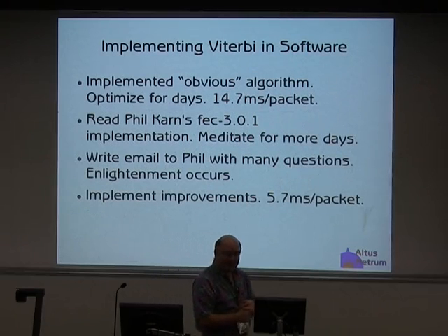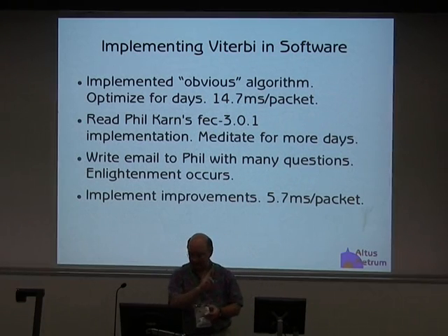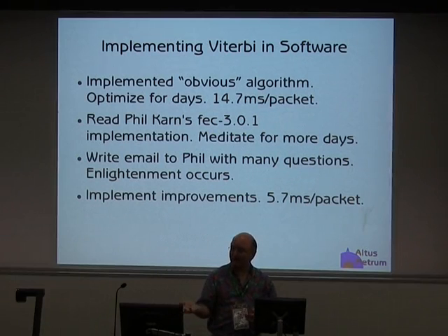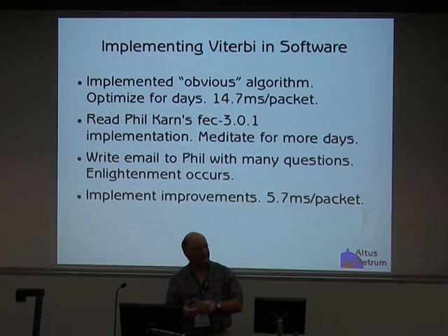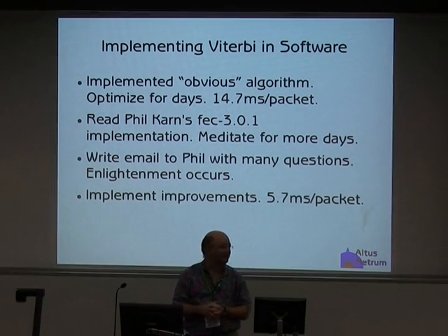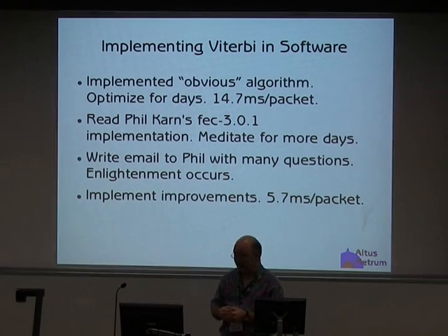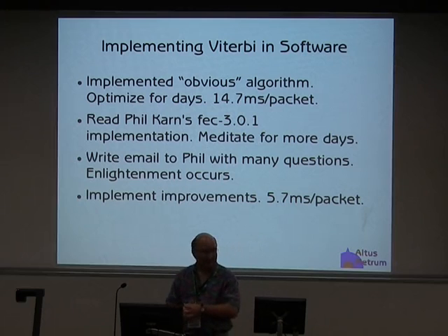Okay, I implemented this in software. I've got 2 more slides. I implemented the obvious algorithm. The obvious algorithm was first decoding packets at a rate of about 1 packet every 1 second on my STM32L. That was probably not going to be good because I'm transmitting 10 packets a second. I optimized that for days. Got down to 14 milliseconds, almost 15 milliseconds per packet.